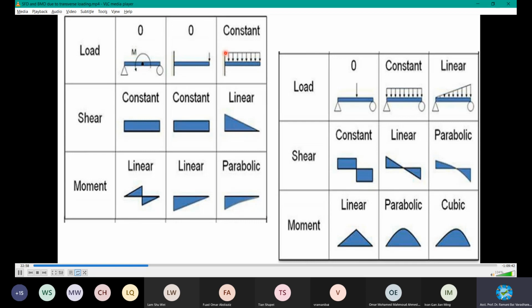It should be a cantilever, fixed here. It's a fixed end, but with UDL acting. Cantilever, UDL acting on it. Because it's fixed, there is a reaction. That's why you're plotting some value here. And then moving on, there is a loading and a response. Why is it tending to incline, decreasing? Because there is no other support or reaction here. So naturally, it will gradually reduce to zero at this point, the free end, because it's a free end.